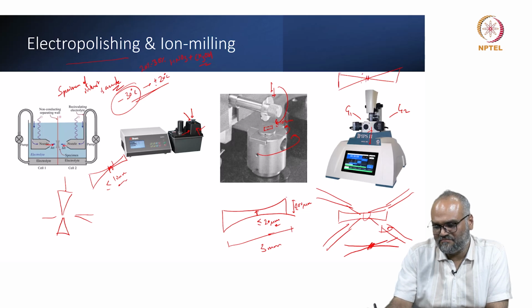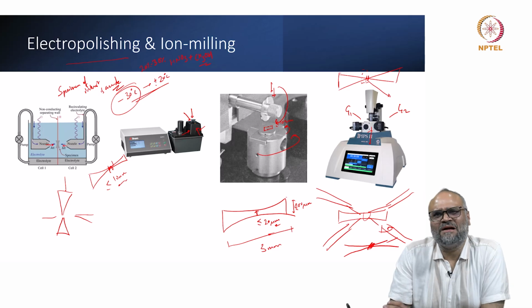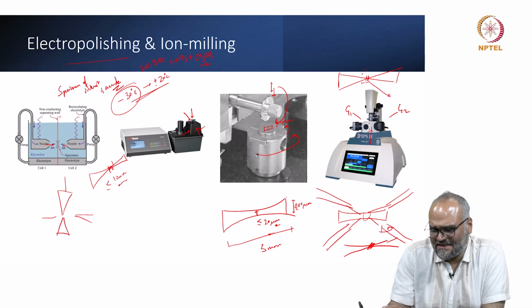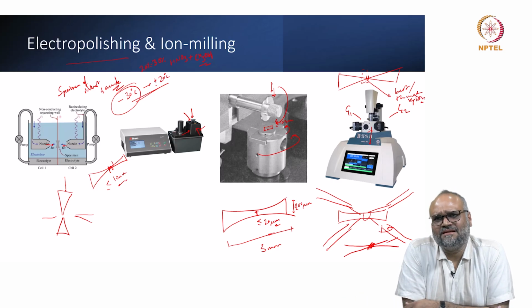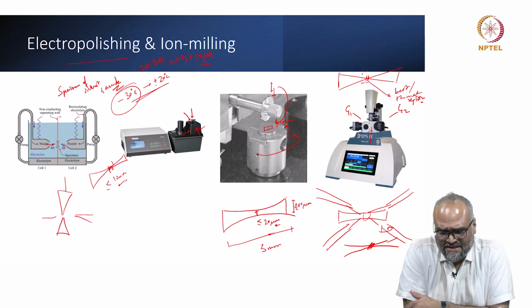You have to search for this hole in a microscope typically, and right next to the hole you have the best, thinnest region. Identifying the thinnest region, orienting it in the right orientation and all matter a lot, and preparing specimens with as low artifacts as possible makes it very important.